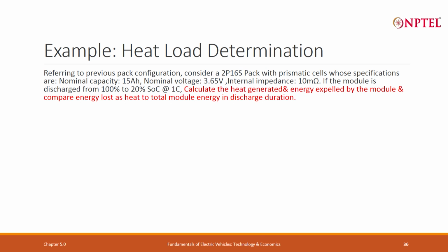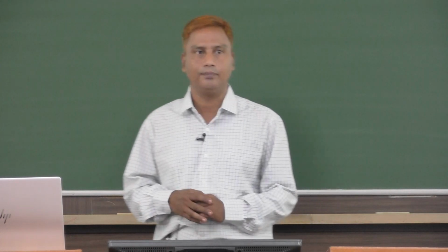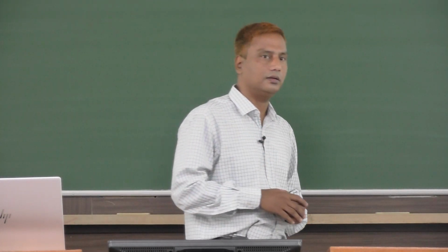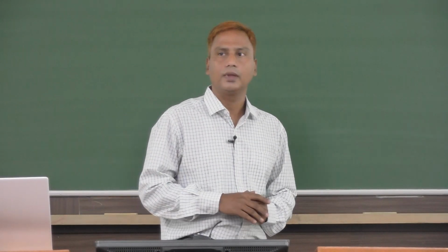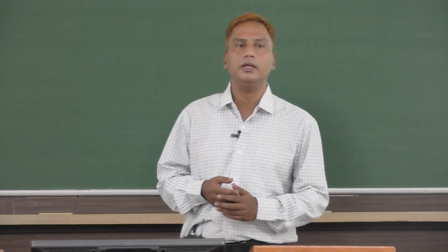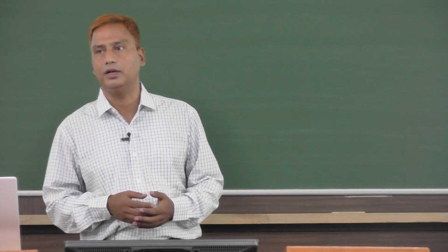The internal resistance of that cell is 10 milliohm, or internal impedance is 10 milliohm. 10 milliohm is generally resistance at higher side, and this you achieve during the end of the life of the battery pack. That means when it has been degraded to 70% of its original capacity or 75%. So, whatever we put is approximately it comes at that. However, for new cells it would be something like between a fraction of milliohm to 5 milliohm.